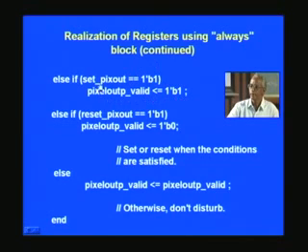And if reset is asserted, then we need to reset it here, and that's what we have put in the comments. If none of these are satisfied, you just use only one else, because this indicates it is the last in that category of else if. In this case, again preserve the same value, so don't disturb the contents.